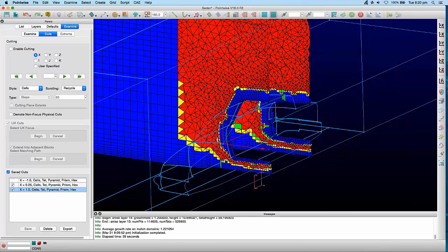So that's one area where I guess optimization, and that's where you'd use something like the adjoint solver results, which gives you surface sensitivity, and then you link that to either a mesh morpher or you could actually come back to remeshing, depending on how complex your geometry was, with Pointwise. If you'd scripted the geometry creation in Pointwise and the meshing, then you could potentially have that come through.